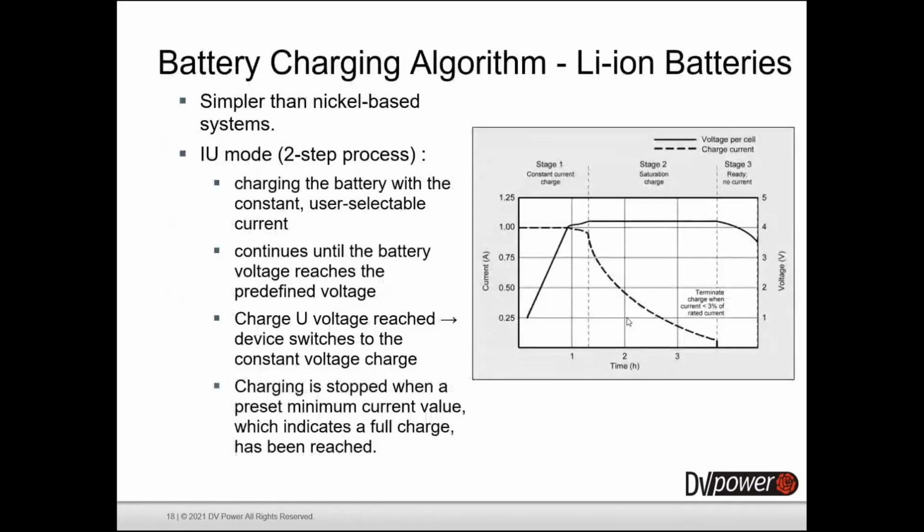While speaking about lithium-ion charging, a lithium-ion charger is a voltage-limiting device that has similarity to the lead-acid system. You will notice that the behavior is pretty much the same, but the main difference is that lithium-ion has a higher voltage per cell, tighter voltage tolerances, and the absence of trickle or float charge at full charge. While lead-acid offers some flexibility in terms of voltage cutoff, manufacturers of lithium-ion cells are very strict on the correct settings, because lithium-ions cannot accept overcharge.